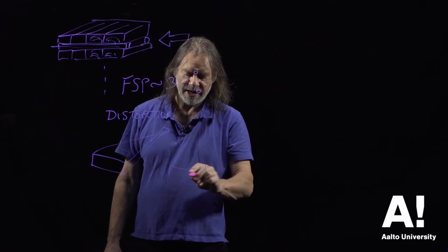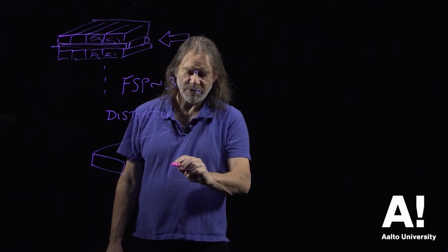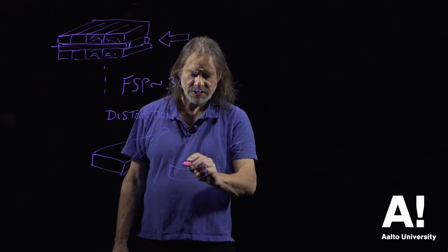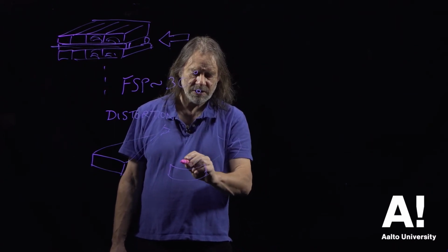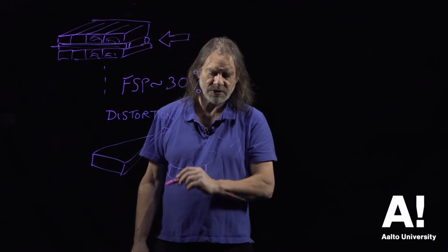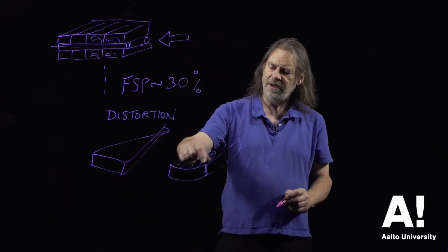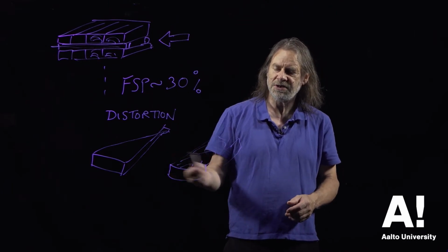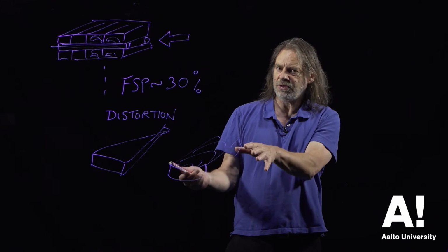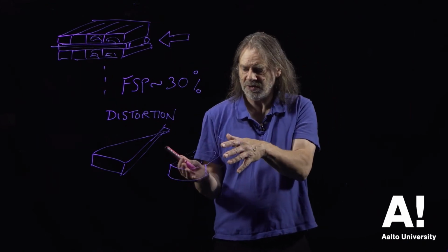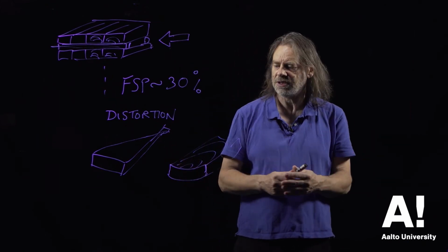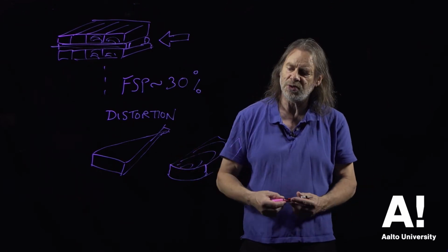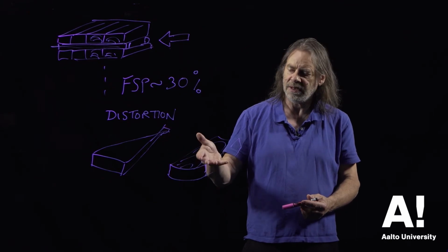The wood can cup. This can be quite common, particularly if the wood is not sawn on the quarter. Then wood that has this sort of tangential face here can be subjected to cupping, and that may even happen in service. If you take wood that has been drying and hasn't shown any cupping during the drying process, you put it into service, it may dry out more in the house, maybe you're using it for a floorboard, and then that cupping will become apparent.